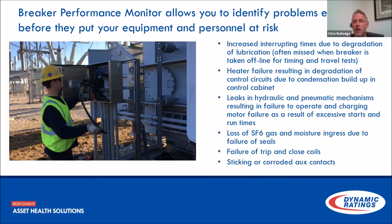Leaks in hydraulic and pneumatic mechanisms, resulting in failure to operate, and charging motor failure, which is a huge one. We had a lot of the old oil circuit breakers at my utility. There were very few stations you could ever set foot in where you did not hear at least one compressor start up every time you walked in. And the same with hydraulic. We had a lot of cabinets that had a lot of oil in the bottom of them. And really, if you're only doing this every 5 years, you can end up having something that does fail to operate due to loss of stored energy.